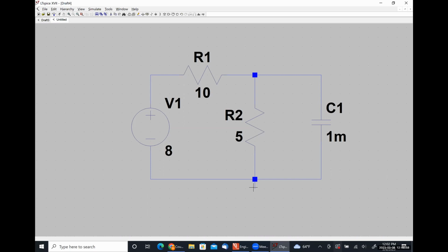I give myself a little stub of wire and then connect my ground to that stub of wire, just because a couple of times LT Spice pissed me off. All right. And now, just for the sake of argument, so that it's really obvious as to what we are actually finding, I'm going to label that node VCs so that I know what to look for my capacitor.